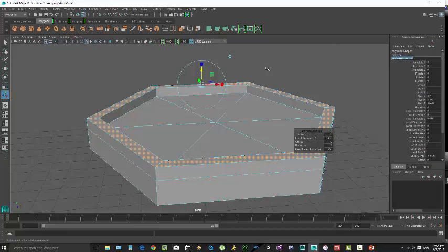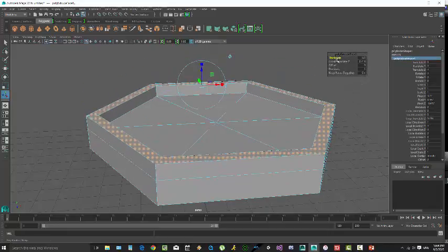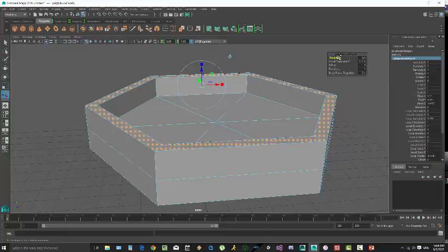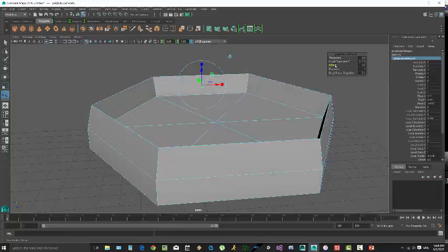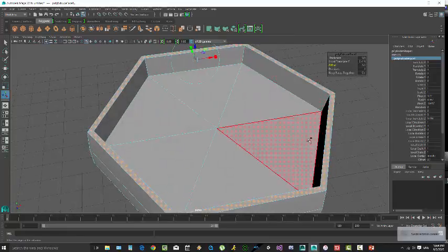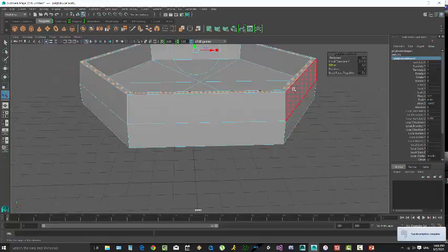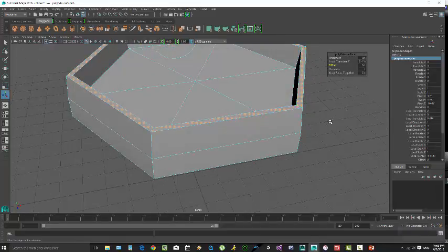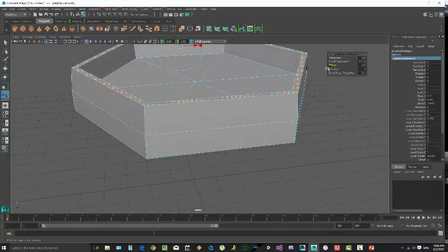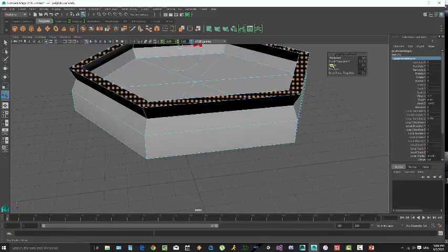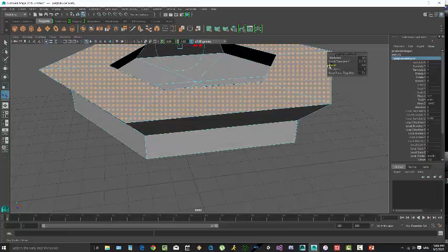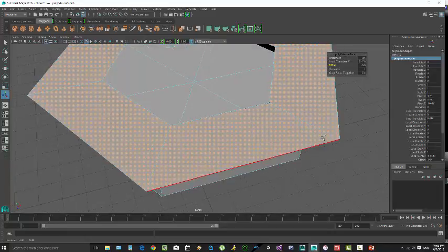But if you would rather change your options, and again, this is new as well, you can change your thickness here on this. I don't even know what the proper name for this thing is because I didn't have this before. You can change your offset, and the offset is the thickness from the end face or polygon in comparison to the one you started in. So you can make it thinner or even thicker, whatever.